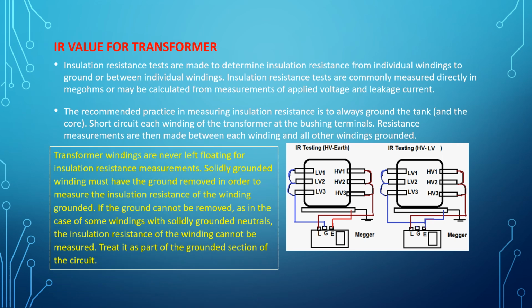Transformer windings are left floating for insulation resistance. Solidly grounded, treat as a part of the grounded sections of the circuit. So you have the idea, guys, how to do the testing for the transformer.